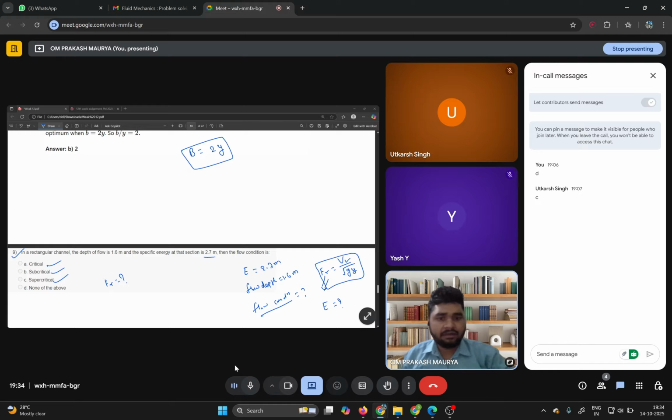Hello, yes, hopefully I am audible to you. So we have already solved the 8 questions. So we are solving question number 9. Please just try to solve. This is related to whether the flow is critical, subcritical or supercritical. You will tell based on the Froude number. You have the data, specific energy 2.7 and your flow depth is 1.6. Please just try to calculate based on this.